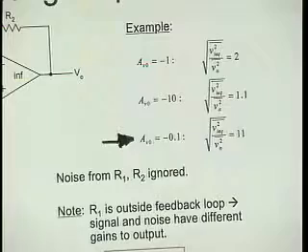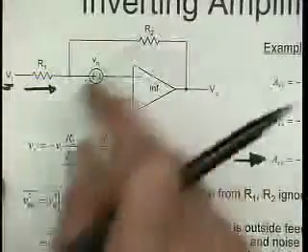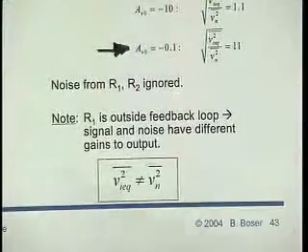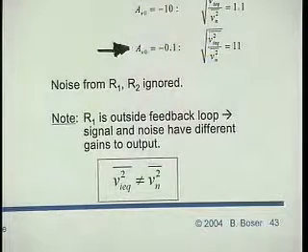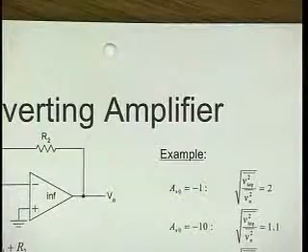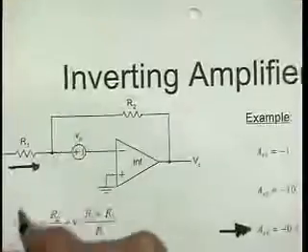So the key thing is that if you have such a configuration, be there resistors here or capacitors here, then not feedback itself, but the compound circuit is certainly going to change the signal-to-noise ratio. As you vary the closed-loop gain of this thing, the signal-to-noise ratio out here is going to vary also. And the reason is that there is stuff that is outside the feedback network.